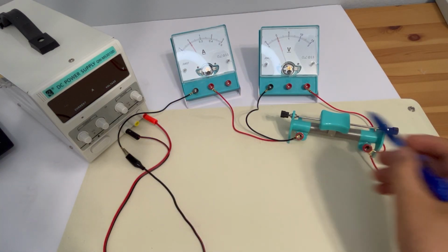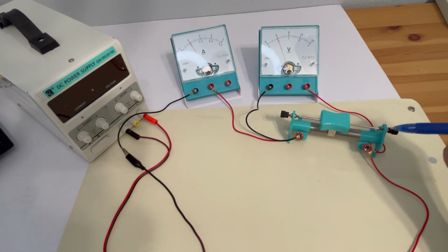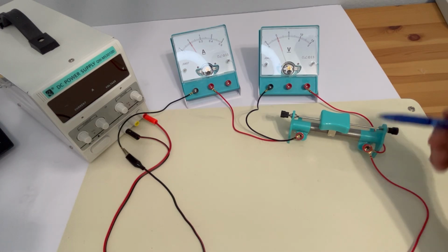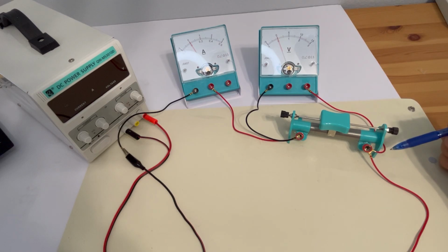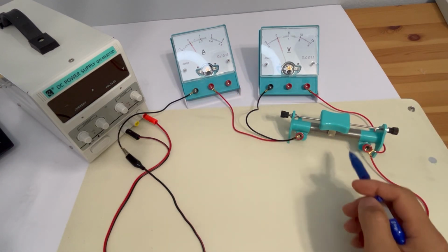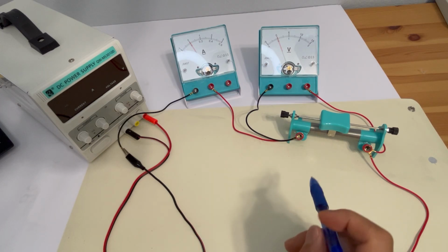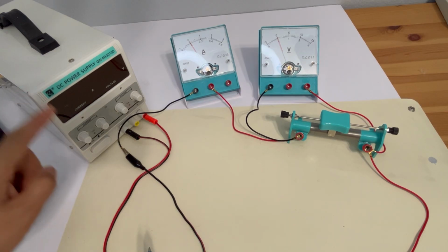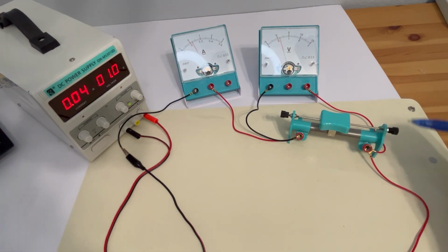We are using a DC power supply that can display voltage and current values itself, so we don't need separate ammeters and voltmeters. However, to demonstrate how to use an ammeter and voltmeter in this experiment, we have included them in the circuit. Now let's turn on the power supply and measure voltage and current. The power supply voltage will increase from 1.0 to 4.0 volts with a step size of 0.5 volts. Here we just show the voltage and current values of the circuit at each voltage step.